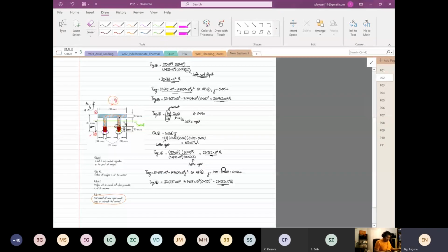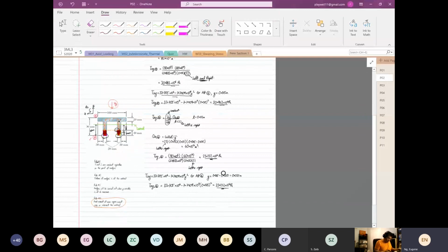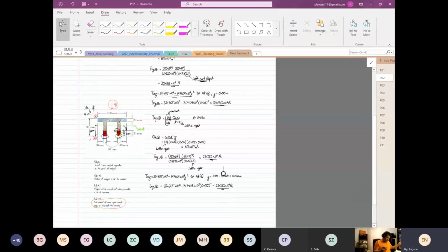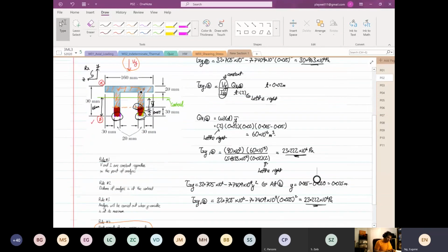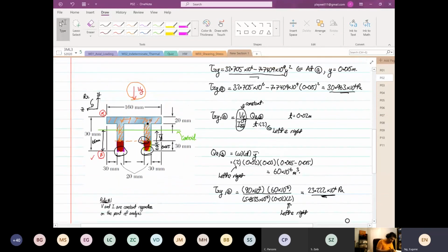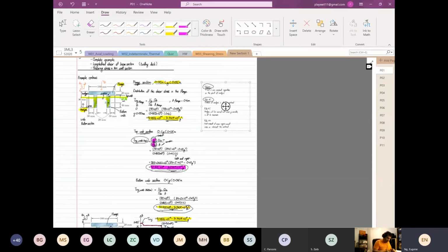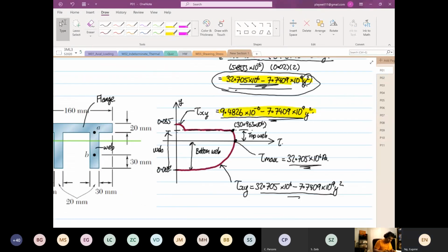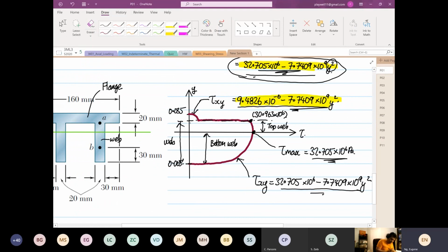So that's why I picked this example. This example seems confusing and tricky, but if you apply the rules, it's not so bad. At point A, what you have learned is that if you want to calculate the thickness at point A, you use the minimum thickness because it's the higher value. Why the higher value? You can see over here, once it reaches the web, it has a step function. It goes straight up, so you calculate the higher value.